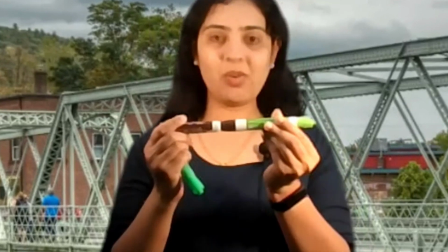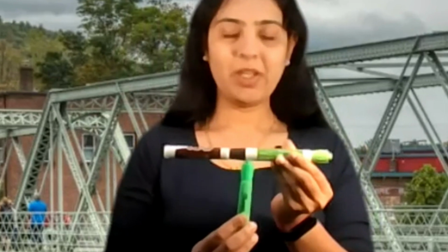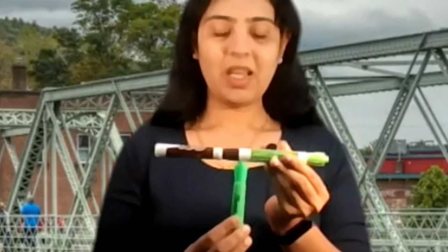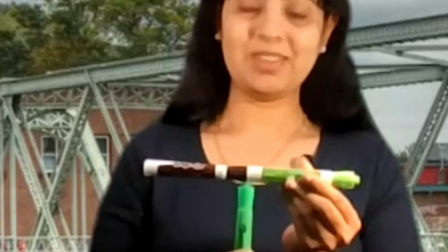Two members are collinear and the third is perpendicular to them, and there is no load on this joint. Then this third member has zero force. It is a zero force element.